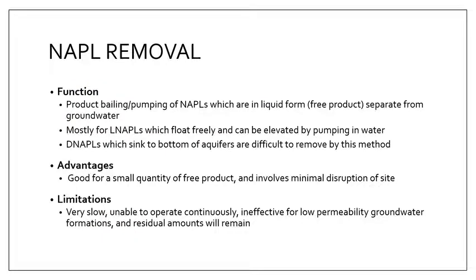The next physical method is the NAPL removal. This is basically just bailing or pumping out. Bailing means you're just scooping out the water. The non-aqueous phase liquids, alright, are typically in the form of a free product, meaning it's a separate phase from water.